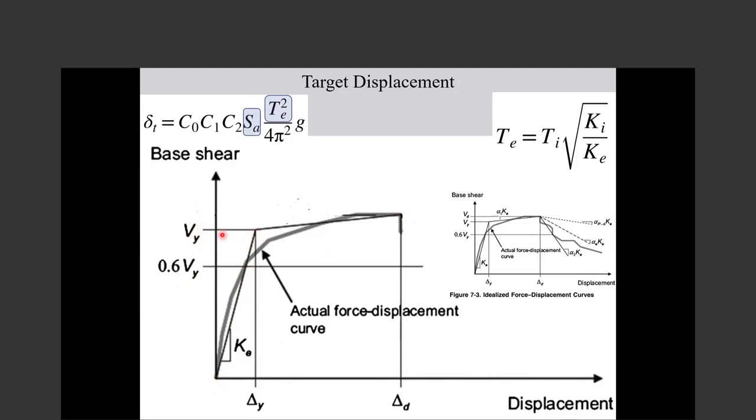At the beginning, people were writing codes in Visual Basic or in Excel to derive these curves. Now the software themselves derive this curve. So they do an initial pushover on the building, then they linearize that by this method and find the equivalent.